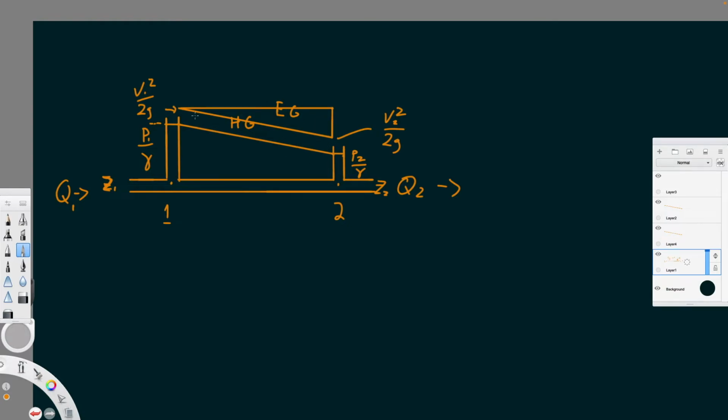The amount of loss of head is, unsurprisingly, known as head loss, and that's this height here. This head loss is basically caused by the friction between the fluid and the pipe wall itself. So the more velocity you have, or the rougher the pipe, the more head loss you're going to have. So let's start putting some of this stuff together.